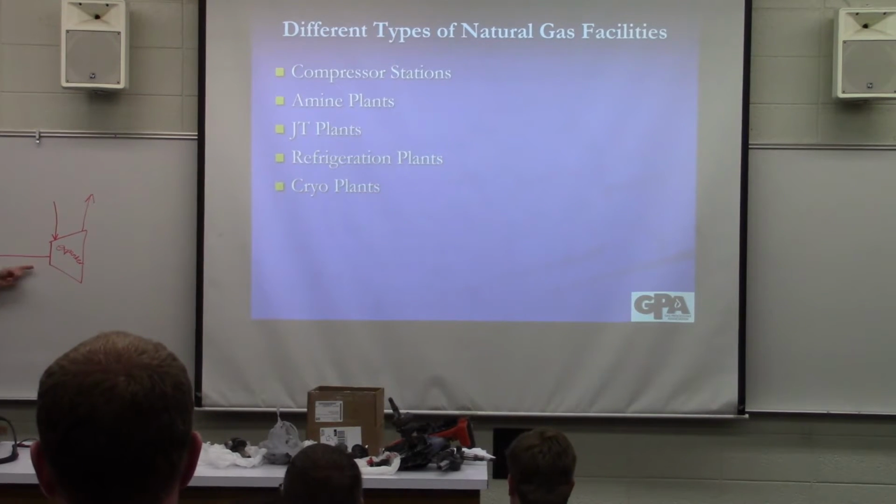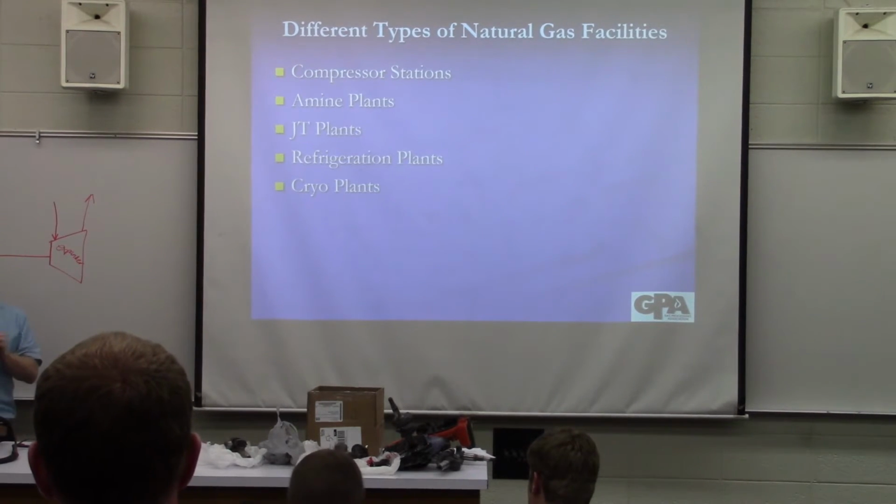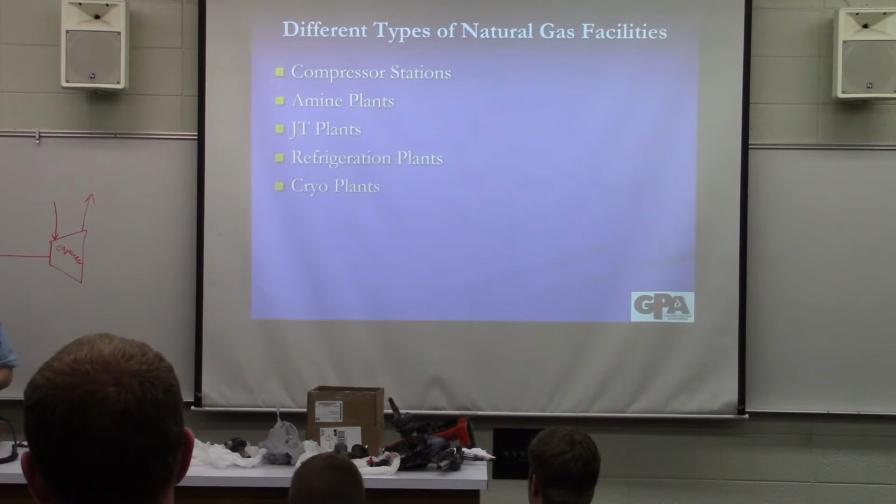That powers a shaft that's physically connected to a compressor. So the same stream, it does some other stuff first, but then it comes in here, and you're using that energy to compress that same gas. It comes in and gets compressed, and that turns out to be a much more efficient way to take an expansion than the Joule-Thomson expansion. And we get into a little bit more of the